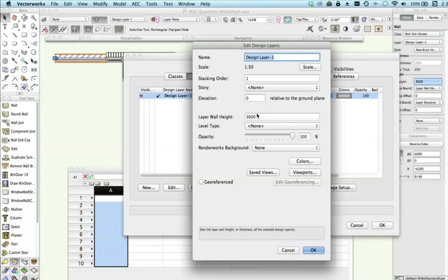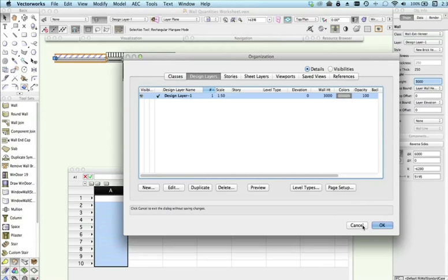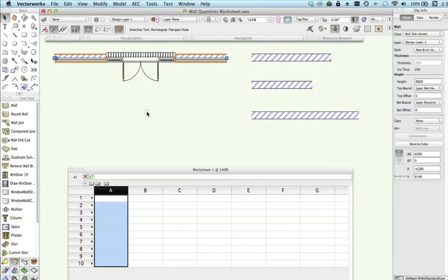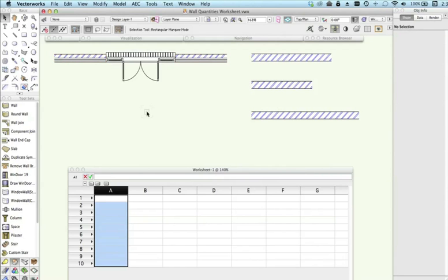If we edit this wall, you can see that's where that number has been entered. So the height of these walls is being controlled by that setting there. There's a couple of different ways that you may want to list walls. One is that you'll just want to get the volume of all walls in a drawing, but you also typically might use a few different types of walls, or have different situations where you want to quantify walls differently.